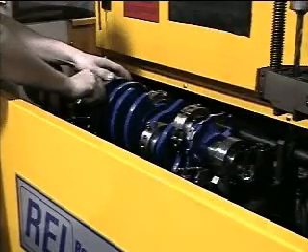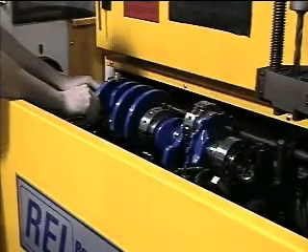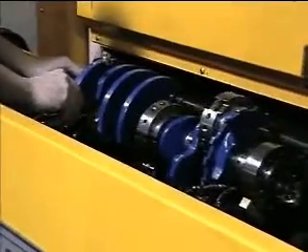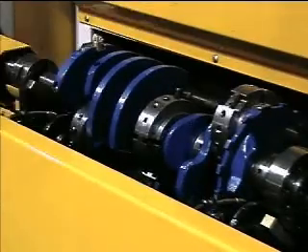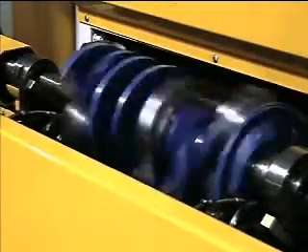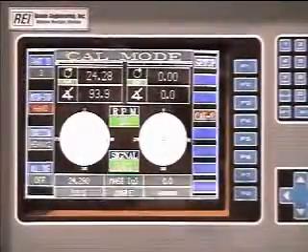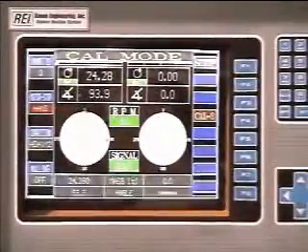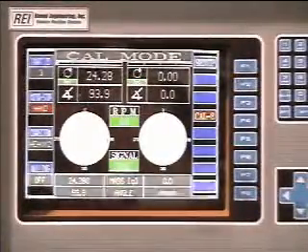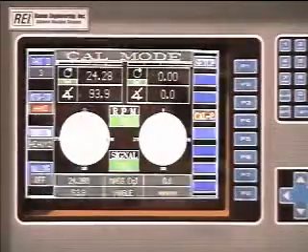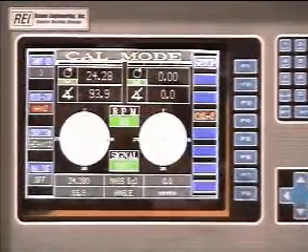This step provided the machine with an electronic zero baseline. The HBI-25 automatically advances to Cal Step 2 when the part comes to rest. At each Cal step, the operator can reset to repeat the previous step. In Cal Step 2, the indication box at the bottom of the screen directs the operator to attach a 24.28 gram weight on the master gauge at an angle of 93.9 degrees.